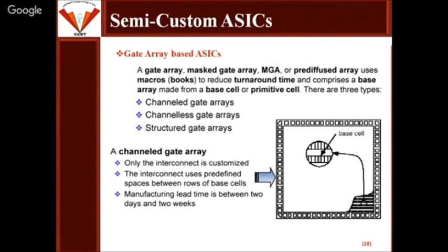We also take into consideration the power dissipation of the devices. If one device has higher power dissipation and another device also has higher power dissipation, we have to place them such that the overall distribution of heat dissipation is uniform. It should not be that one part of the chip has higher power dissipation and another part has very low power dissipation.